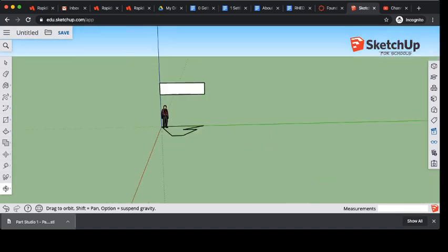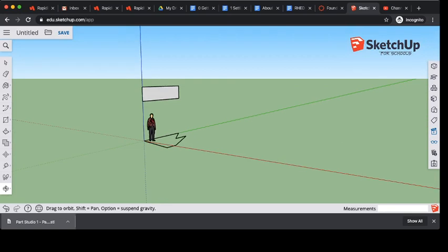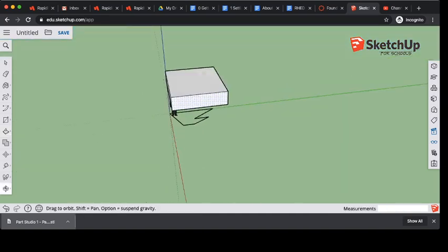The shading in tells you whether or not you're able to extrude that to make it three-dimensional. Underneath the rectangle tool, there's this thing called push-pull. Push-pull is like what the extrude was in Onshape. If I select the push-pull tool and have one of these shaded-in surfaces, I can click on it, and it'll drag it out and make it three-dimensional.